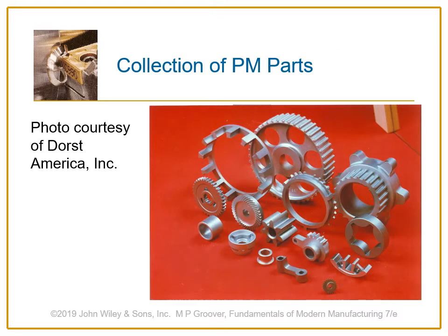These are some examples of parts that are made using powder metallurgy. So you can see a variety of products, sizes and shapes that are made out of powder. And here we must not forget to remind you that in that type of processing, we apply pressure and heat, but that heat is under the melt temperature.